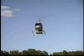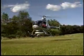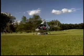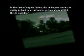To get the helicopter back on the ground, we need to move the cyclic back enough to slow down and stop. Then lower the collective and reduce the throttle to settle onto the ground. The ability of the helicopter to land in limited spaces also gives it a unique safety benefit. How do you think this is possible?